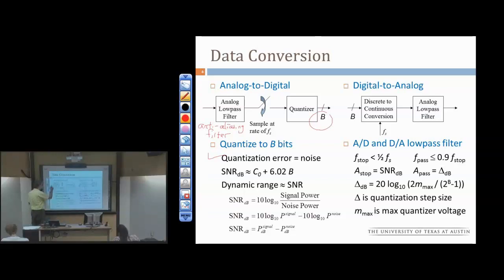from input to output for the A to D converter, we would really like to have the converter matched in terms of quantization noise to the thermal noise in the system. All right, so what that will mean is if the quantization noise is equal to the thermal noise, how good are the bits? Are all the bits good down to the least significant bit if we match? If we match thermal noise with quantization noise, they're equal. Same noise floor. Are all these bits good, or do we still lose some bits?